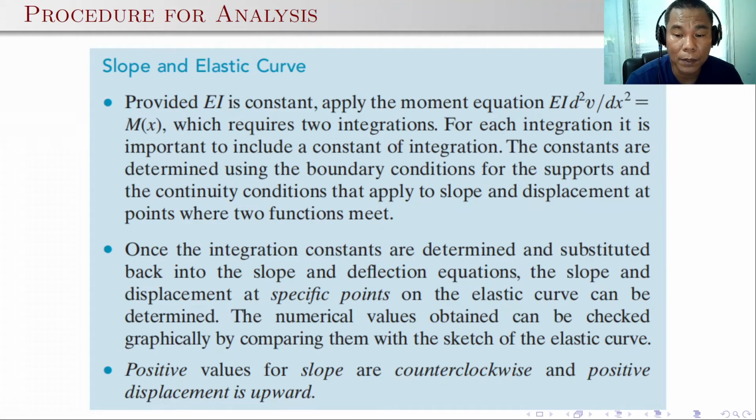The numerical values obtained can be checked graphically by comparing them with the sketch of the elastic curve. Positive values for slope are counterclockwise, and positive displacement is upward. Take note of this.